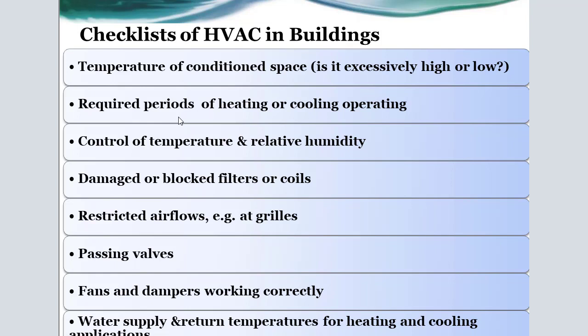Also required is calculation of the period for heating or cooling operation, and control of temperature and of the relative humidity inside the space in the building, and also checking for damaged or blocked filters or coils, which must be maintained or replaced, or advice given about cleaning them.